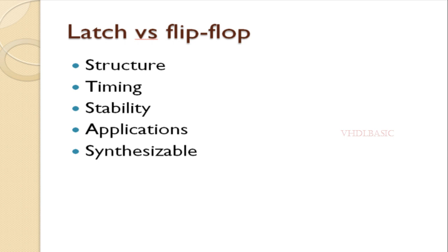This can lead to potential timing issues, especially in complex circuits, as the output may change unpredictably based on the input signals. Flip-flops, being edge-triggered, are synchronized to the clock signal and update their output only on the clock edges. This provides more precise timing control and avoids glitches that can occur in latches.